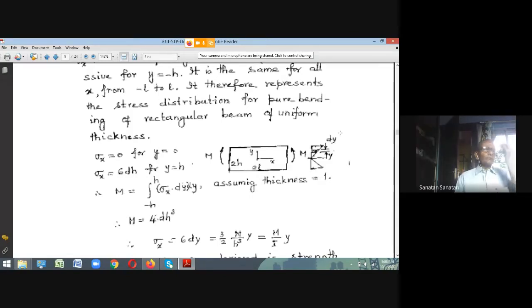You see, we have shown exactly that irrespective of the form of phi, it could be anything involving x and y. But you must make sure that the form you have selected has some arbitrary constants. Those constants should be such that they satisfy the specified boundary conditions, and they should also make the equilibrium equations satisfied, provided they have certain linkage, certain values. So that's what constants you must select.